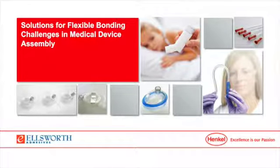So clearly there are going to be cases where the performance is equal between solvents and adhesives. I'm sure there are cases where one may leapfrog the other slightly, but in that particular case, it was a PVC case, and the adhesive did significantly better than the solvent. Again, it would depend on substrates, joint design, and certainly some other environmental factors if it was going to undergo some kind of exposure.